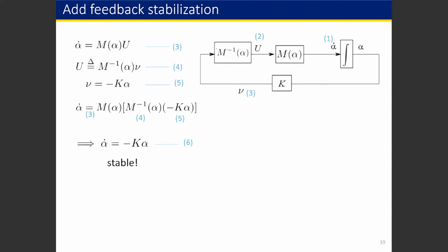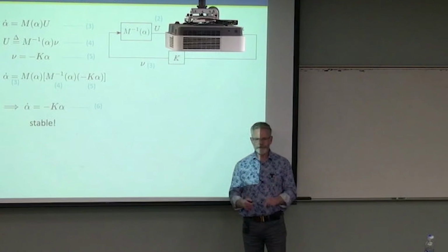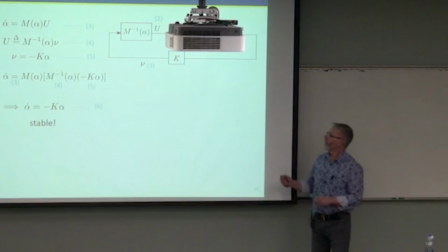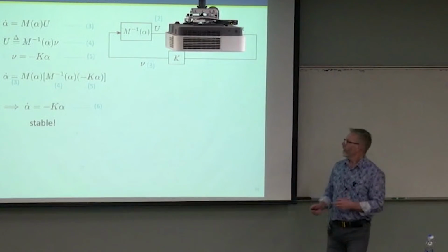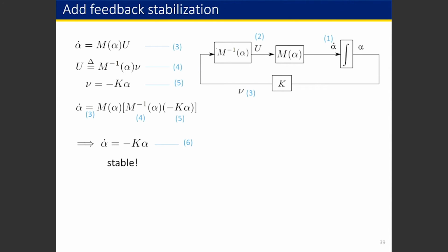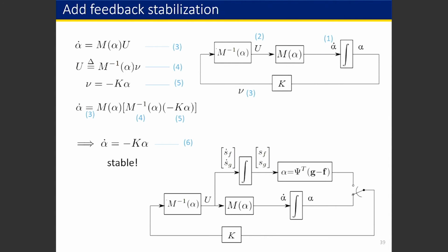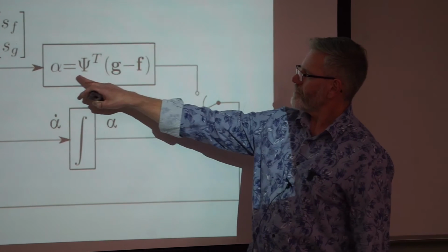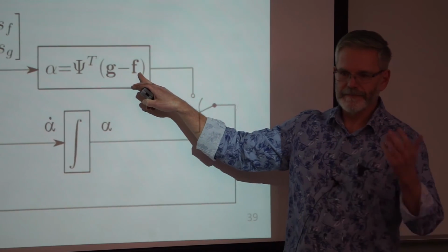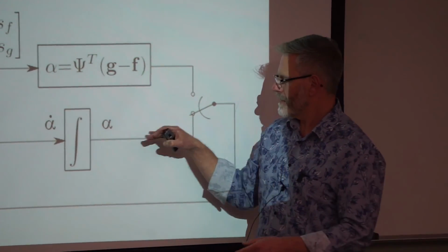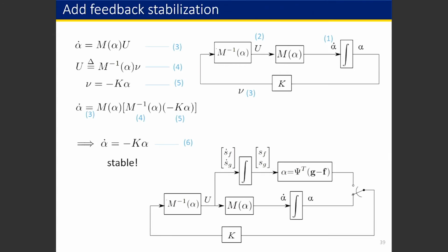And here we are in the kind of block diagram. This is super simple. I might remind you of feedback linearization. That's what this is, in effect, in a simplified sense. And there's a trick I can do. I don't really need to integrate alpha dot if I don't want to. I can express alpha if I've got the forward kinematics. Just by the way, not a big deal, but it's a nice debugging tool.